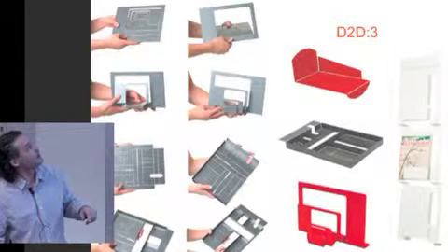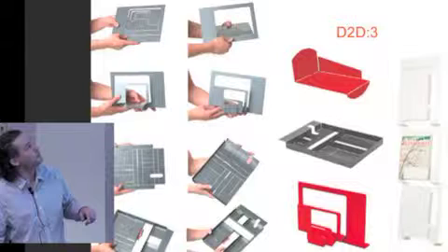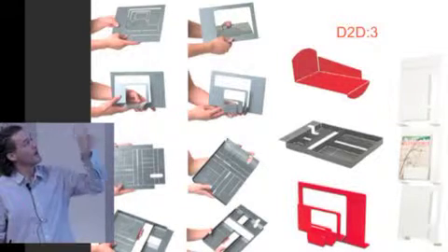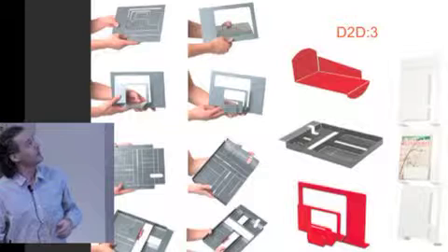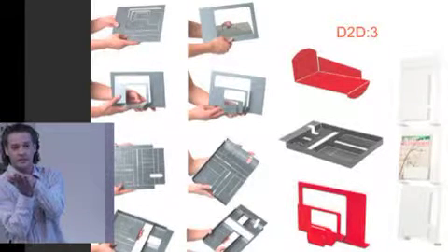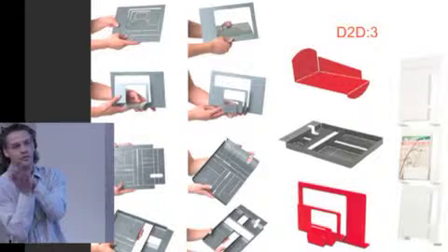This is cut out by a computer-controlled tool called a laser cutter, and then it's punched with a turret punch. Then that piece is hung on a rack. We make these in the hundreds, and they are powder-coated. Then they're put in a kind of envelope-type packaging. So this thing stays flat the whole time. It's one piece, all holds together, no fasteners.